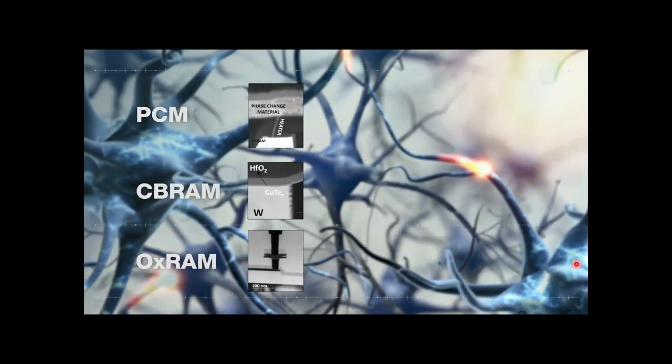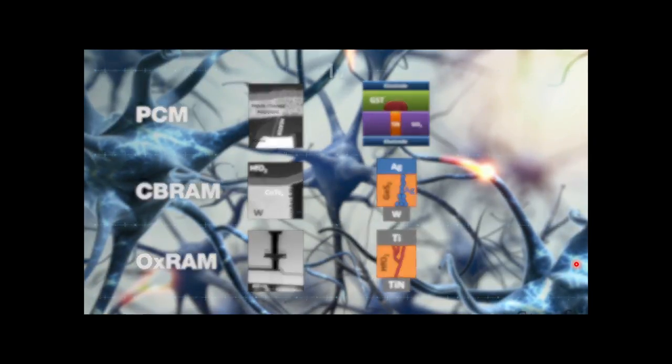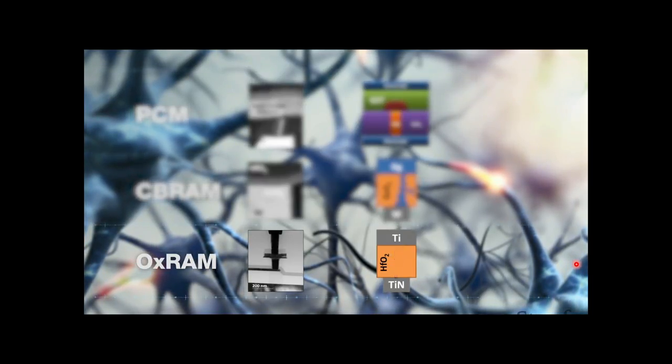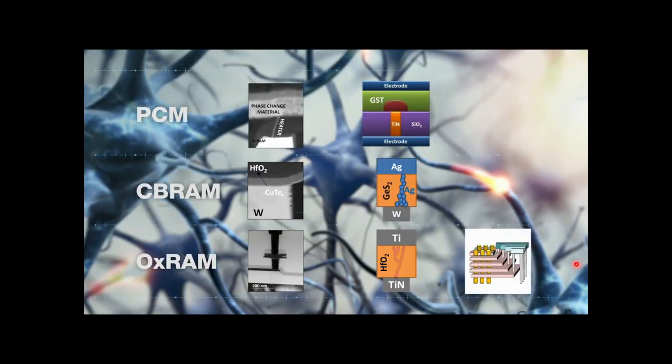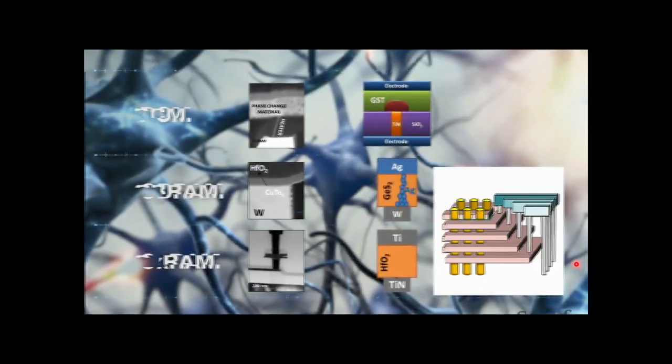Non-volatile resistive memories are promising components to simulate synaptic behavior. Leti is developing resistive random access memories, such as phase change memories, conductive bridge memories, and vertical oxide-based memories. The variation of their resistive state enables information storage. These technologies offer non-volatility, precise conductance modulation, and high density of integration, needed to model synaptic behavior.